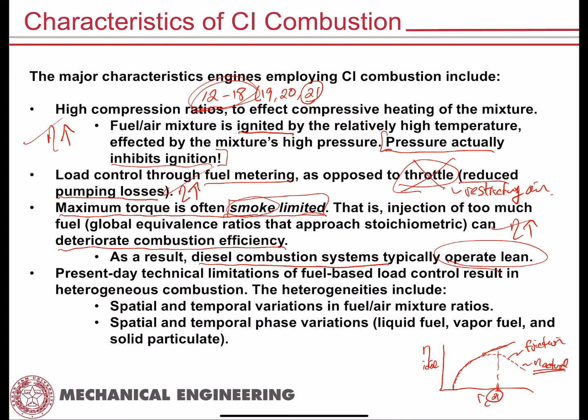And that's why, quote unquote, diesel engines are considered more efficient than their spark ignition counterparts. It's nothing to do with the fuel. I've heard people say that, right? They'll say, well, diesel engines are more efficient because diesel fuel has a higher heating value. Absolutely not true. First of all, as you've already seen, diesel fuel and gasoline have almost identical heating values, which makes sense because they're both composed of long-chain hydrocarbons, right? So that's where your heating value is basically coming from, the nature of the hydrocarbon.